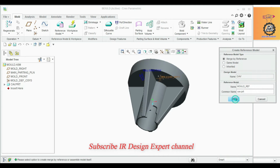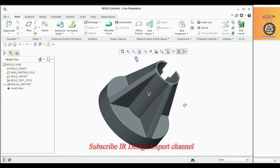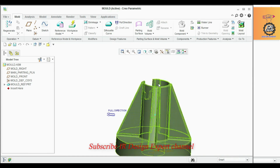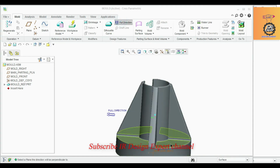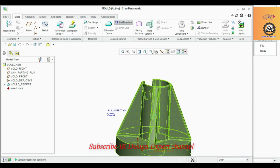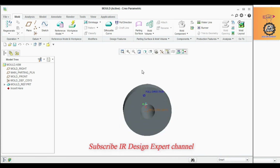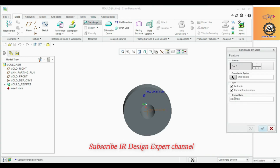This is made the reference. Okay, and we can change the pull direction. So the direction is here, the pull direction is here, so we can change the pull direction for this surface. Okay, pull direction is changed, and then we will give a sinkage, so 0.005 mm.